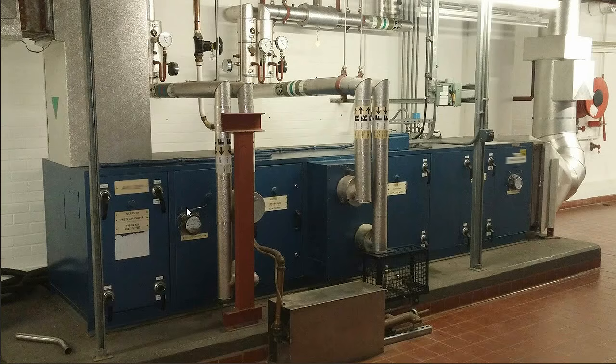It's coming in, it's being filtered. You can see you've got the pressure gauge here, and we'll look at each part of this more later on as well. Then we've got the heating coil here. You can see you've got the flow there, and then it's returning. And then we continue, there's another panel, access panel here, and then it hits into the cooling coil, and that has the flow here and return going along. We've got some pressure gauges there, and then it continues through here.